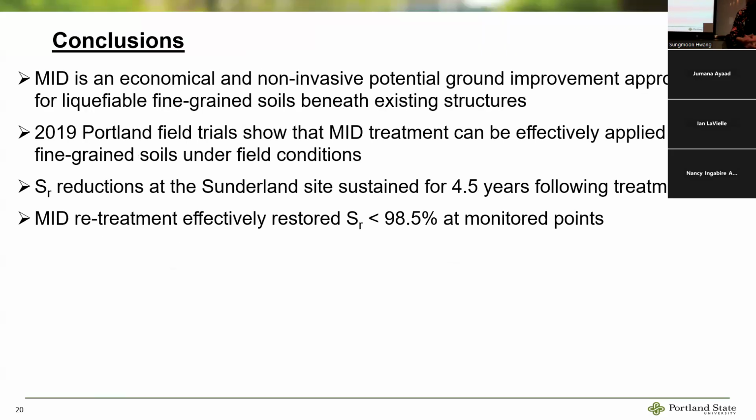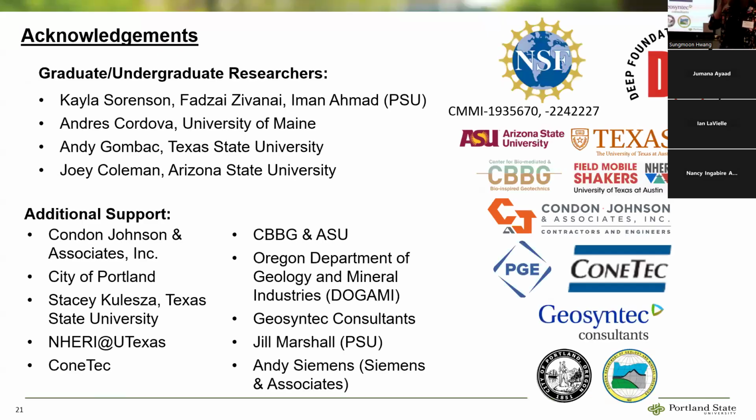So our conclusions from this work: we know MID is an economical and non-invasive potential ground improvement approach for liquefiable fine-grained soils beneath existing structures. In 2019, we showed that it could be effectively applied to fine-grained soils, and that those reductions in saturation were sustained for about 4.5 years. And then we saw that our retreatment this summer successfully restored saturation below 98.5% at the points that we were monitoring.